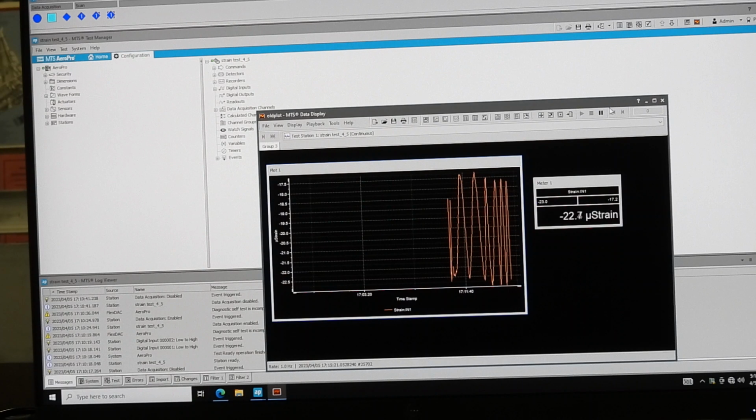Same thing with reading from the inclinometer. We need to ensure that our common signal is referenced to something that we care about. Otherwise, we're measuring a floating signal. We can't do a non-referenced measurement, or we can attempt to, but it's a voltage from a source that is referenced to its common, which goes somewhere else. We need to measure across those two terminals, or else the signal floats around.